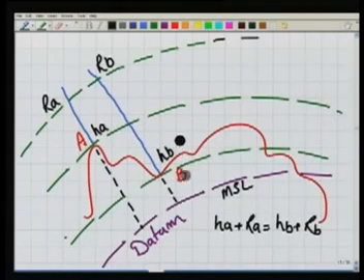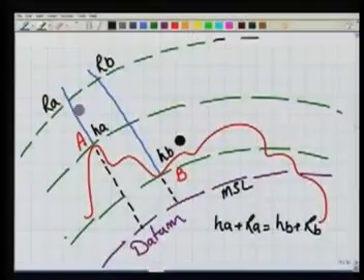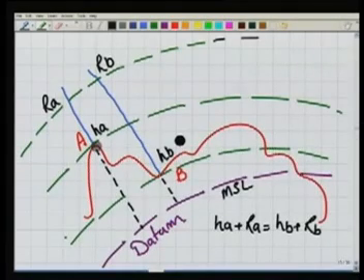In order to do that, because my area is big, I cannot take the horizontal plane. Rather, at B I draw a surface which is parallel to mean sea level, that is, the surface passing through B is a level surface.